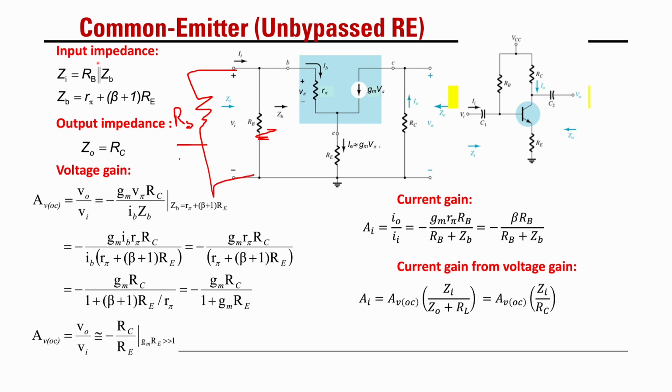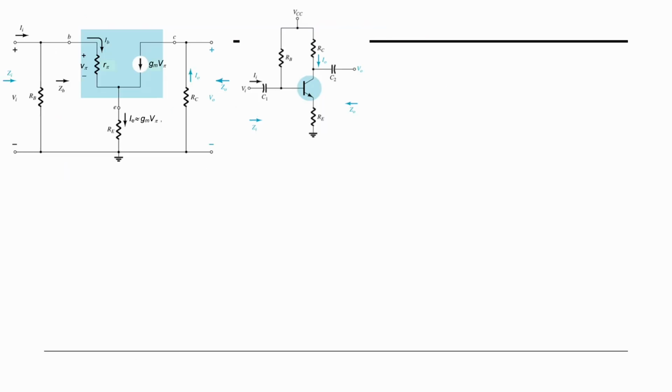All right, now let's look at how we can get the equation. Let's discuss how we get the equation. Let's look at the structure of your hybrid pi model, the equivalent AC small signal circuit. You can see here we have R pi, we have V pi, and this is your resistor at the base, your base resistor.